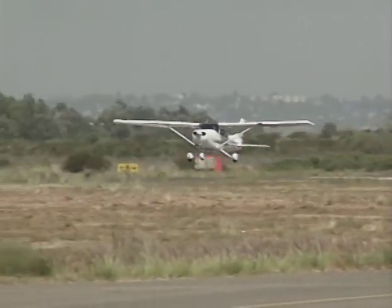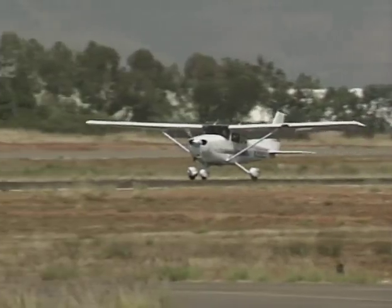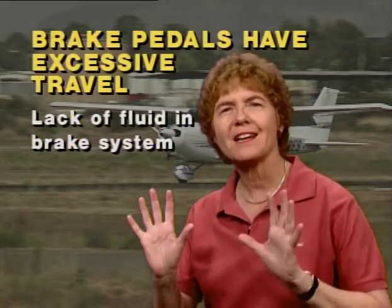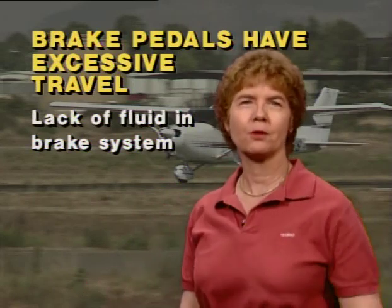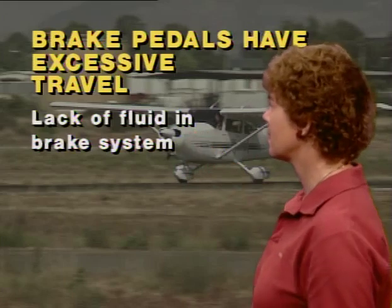Now, let's suppose that a pilot who's just landed doesn't like the way his brakes worked on landing. And the complaint that he comes into you with is that the brake pedals have excessive travel. They go down too far before they grab hold. The probable cause of that is a lack of fluid in the brake system.